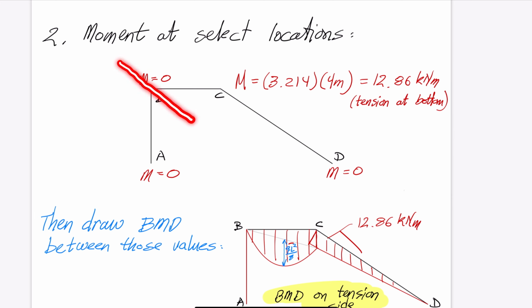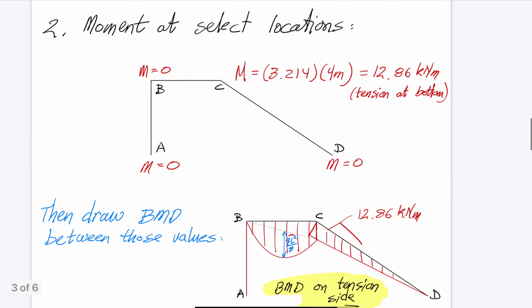Some students try to guess the deflected shape of the structure and speculate about how the bending moment diagram might look like. That is an error-prone approach. It is better to use equilibrium explicitly. Remember, equilibrium is all we need for statically determinate structures in order to determine the internal forces.